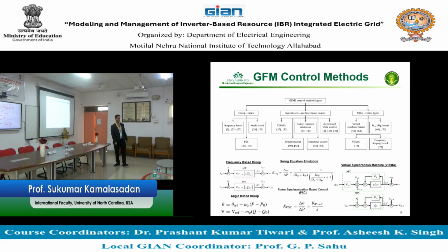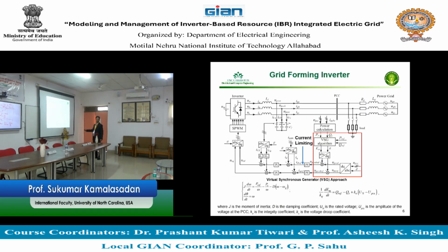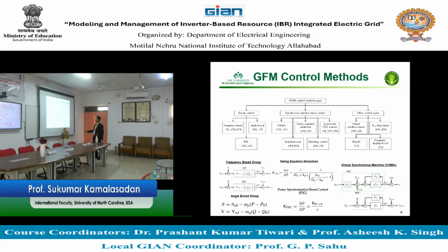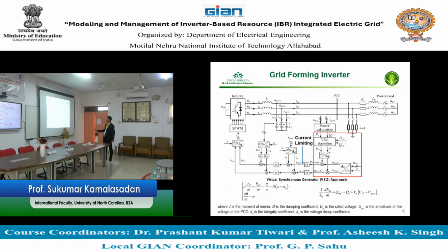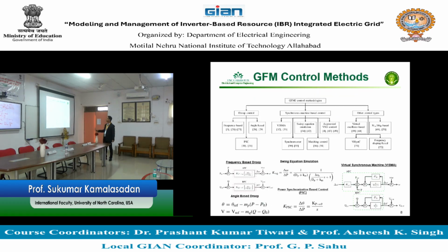Well, I'll give you a sketch. Let's see. This whole box here can be designed in many ways. This many types of work are done in the literature, or maybe more. This box is generally designed in two forms. One is called droop. Second is synchronous generator. And there is a third type borrowed from communication folks called oscillator principles. So, virtual oscillators. You can create an oscillator.